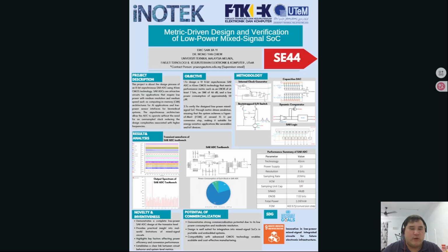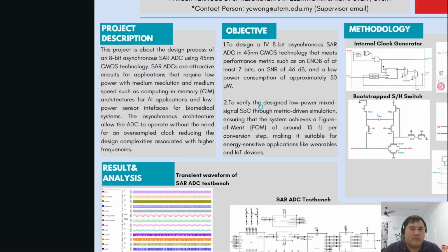The project is titled Metric-Driven Design and Verification of Low Power Mixed Signal SoC. This project is about the design process of an 8-bit asynchronous SAR ADC using 45nm CMOS technology. SAR ADCs are attractive circuits for applications that require low power with medium resolution and medium speed, such as computing-in-memory (CIM) architecture for AI applications and low power sensor interface for biomedical systems. The asynchronous architecture allows the ADC to operate without the need for an oversampled clock, reducing the design complexity associated with higher frequency.